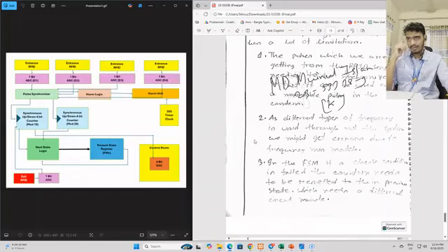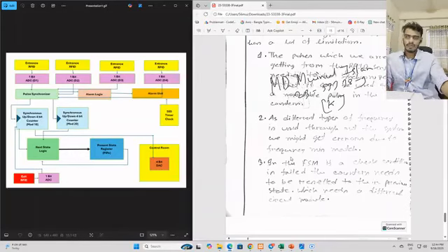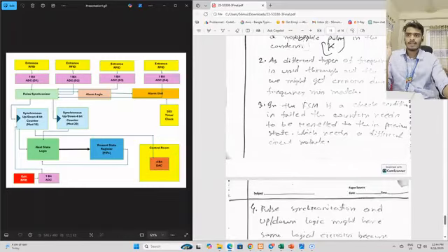I have said earlier that if the FSM gets more than 10 counts, it will reset to 000 as a counter property, but we cannot reset it to 000, because we also need to stop the next passenger who is coming, right? That's why we need to reset the counters to the previous state, the 19th state. So we need an extra module for that, but I did not implement it here, as this is also not a requirement for the assessment. These are limitations.